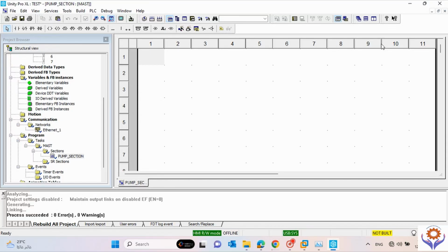Once you create the ladder logic, you will find the supporting tools here, like selection mode, escape. Here normally open, normally closed, positive transition and negative transition, and also the coils: negative coil, set coil, reset, positive transition coil, negative transition coil, halt coil and call coil. This one is for boolean connections, this is for vertical connections, this is the link between the connections, this is for operation, and this is for compare block. You can also use jump label, return, and these functions for data selections, and also link and toggle pin.